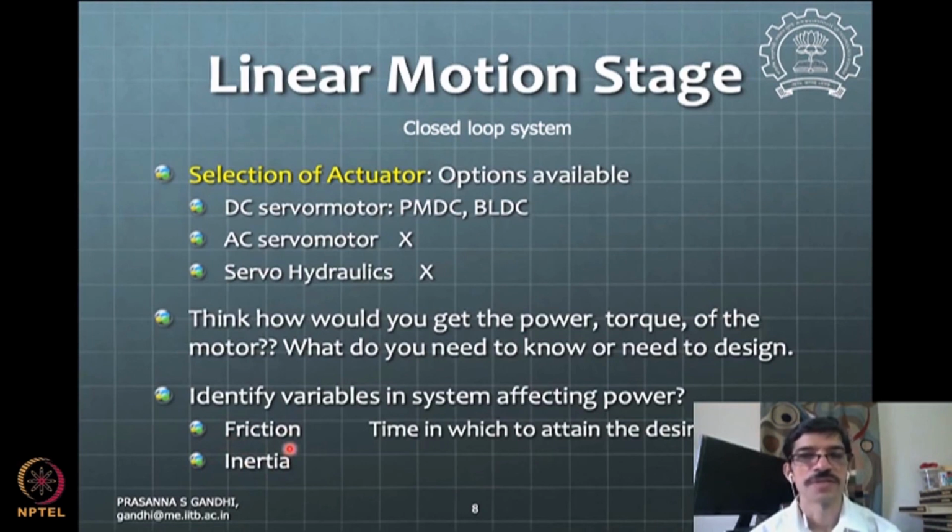To enhance accuracy, or for backlash consideration, you pay a cost: the extra power you have to put into the system to overcome the additional friction that happens because of the spring loading of two elements.